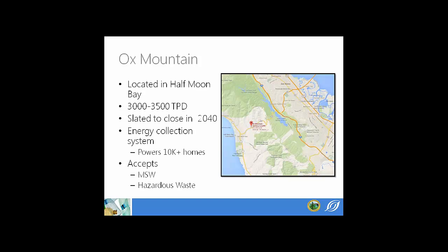It's actually been a lined landfill since 1993, so prior to that, it wasn't. It has a leachate system that collects nearly 30,000 gallons per day of leachate, which is treated. It also has 1,700 poplar trees on site, which actually use the leachate as their water source. So that's another way to use that.